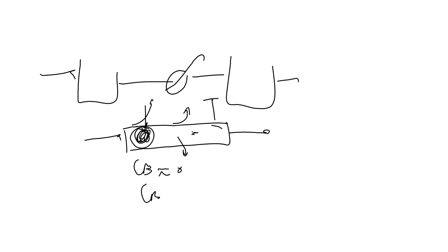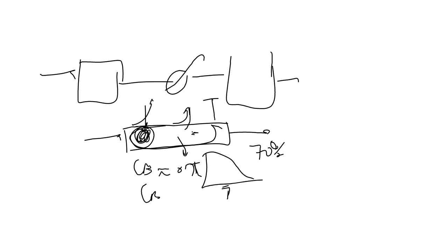So I can actually drive my reaction much further, let's say to that 70%, by cooling in a plug flow reactor and then actually choosing my path on this XT diagram. So that is what we will explore. But if you are limited and you were told that this is the setup that you are interested in, then yes, there is in fact a better option. Okay.